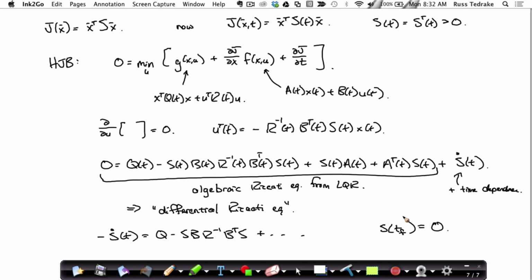Okay, so I can actually solve the LQR problem by integrating backwards in time my differential Riccati equation, and it will find an S. There's a unique positive definite S solution that will give me the cost to go here, which satisfies the Bellman equation. Okay, what does that mean for you? For a user, what that means is you have to design the LQR controller.